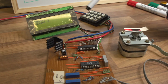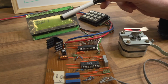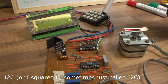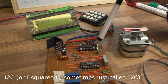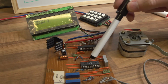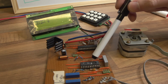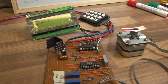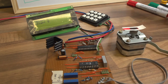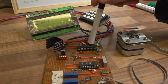And you have to remember, the whole point of this is that this controller chip is doing absolutely everything. It's sending data to the screen through an I2C interface bus, two wires, which is a serial information system. Very simple, just two wires. It's also sending the control signals to the motor controller chip, the buffer chip, which is working on 24 volts at the moment, and that comes through this cable here through a connector to the stepper motor. So the whole thing, the keyboard, the LCD display unit, and the motor, is all being controlled from this chip.